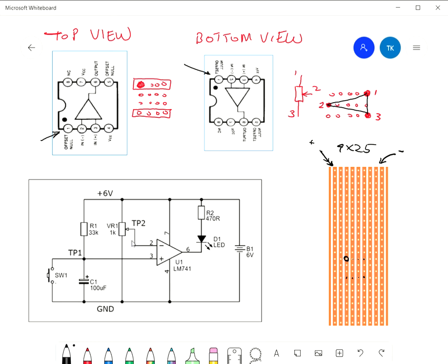Now, when we place it there, because this is a strip of copper, we don't want the copper to be connecting these two pins across. So we will be using a strip board cutter eventually, and we will cut it above the row of holes there. So we cut the strip of copper at the holes in the board there. Okay, so in this case, what we're going to do is we're going to cut it here.